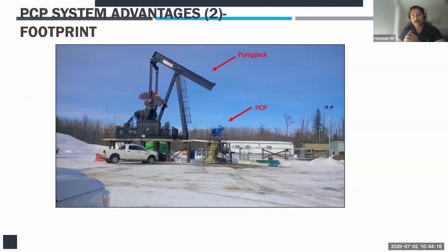One thing I forgot to mention is that this is a positive displacement pump. That means it will keep on producing pressure if there is a flow line restriction. If you close your flow line valve, it will keep on producing pressure until it bursts the flow line, or it will damage the pump. But if you want to talk about the maximum a PCP can produce, it can go all the way to 36,000 kPa.